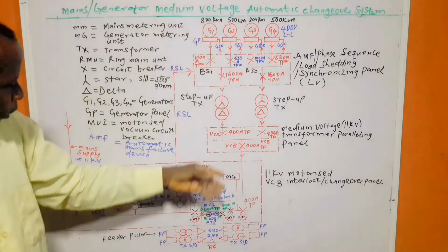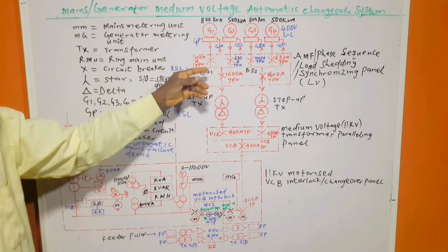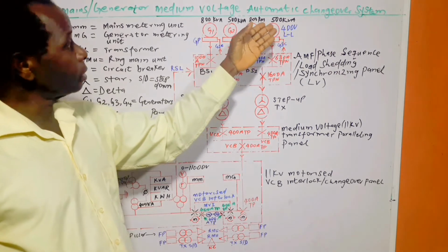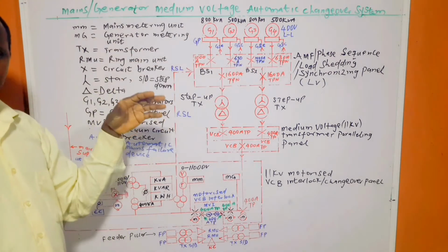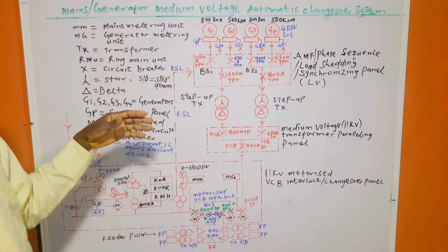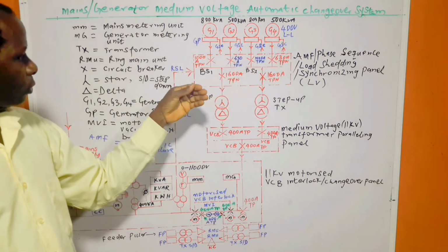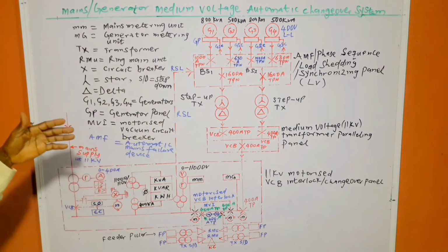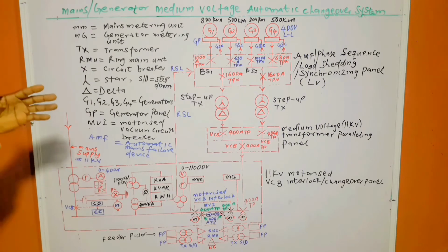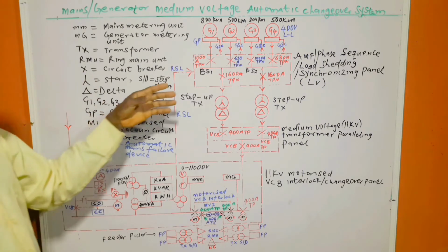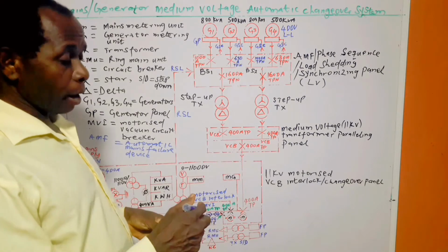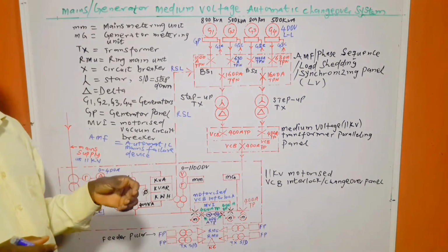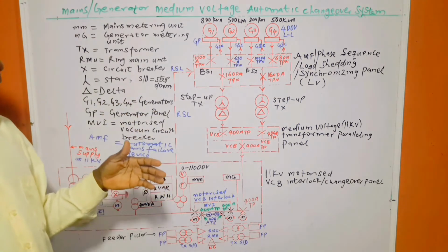Now, the total power being generated is about 2.6 MVA. The current of 2.6 MVA is about 3,753 ampere, which cannot be handled by the 3,200 ampere triple phase with neutral circuit breaker that is readily available in the market.